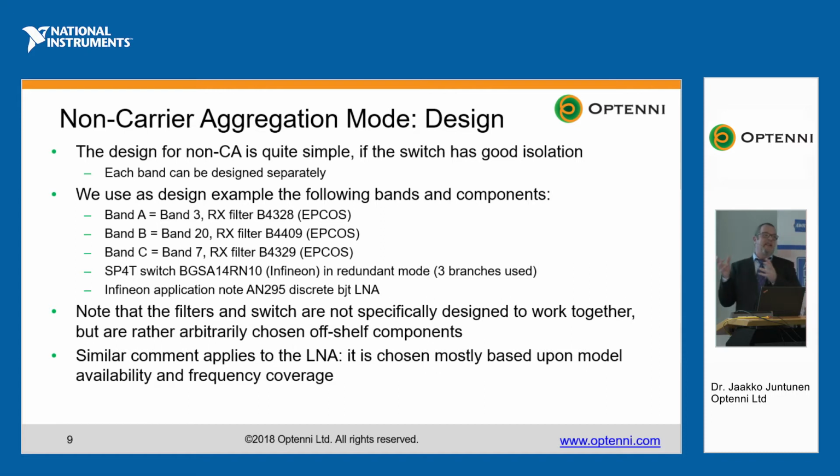This set of components is not specifically designed for this particular carrier aggregation application. I think this is not necessarily the most practical setup. This is a more challenging setup, where you just take some filters and try to guarantee that they work together. There are probably more professional filter designers in the audience. I think the filters can be designed upfront to serve a given constellation in carrier aggregation. As an LNA, I use an Infineon application note that is available in Microwave Office as well, and that choice is mostly based upon model availability and frequency coverage.